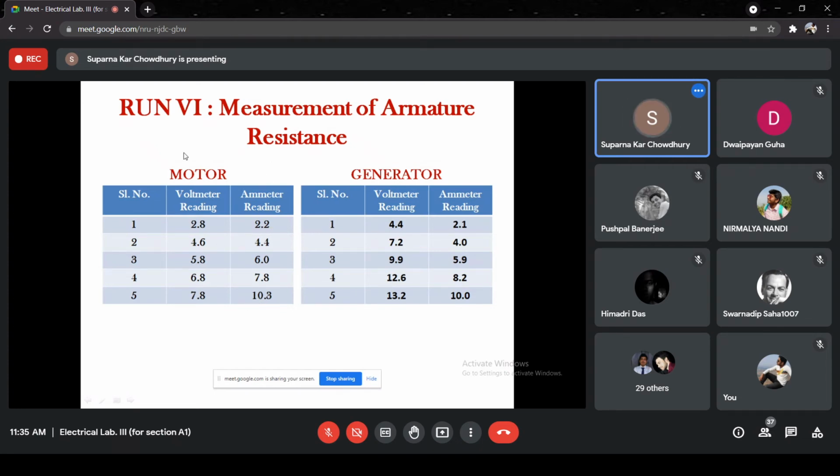That's why we perform the resistance measurement at the end, so that the temperature has risen and the resistance has dropped. But while performing the experiment for different currents, you can see that the resistance is also decreasing. This drop is not due to the temperature rise.